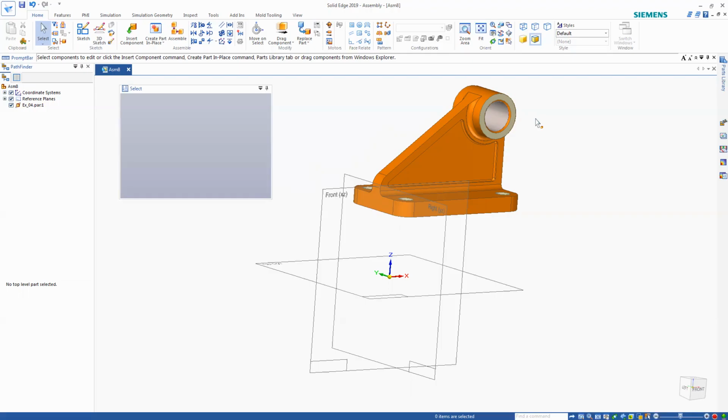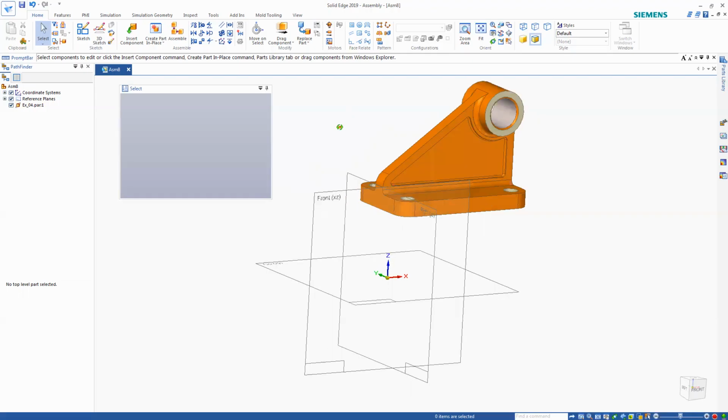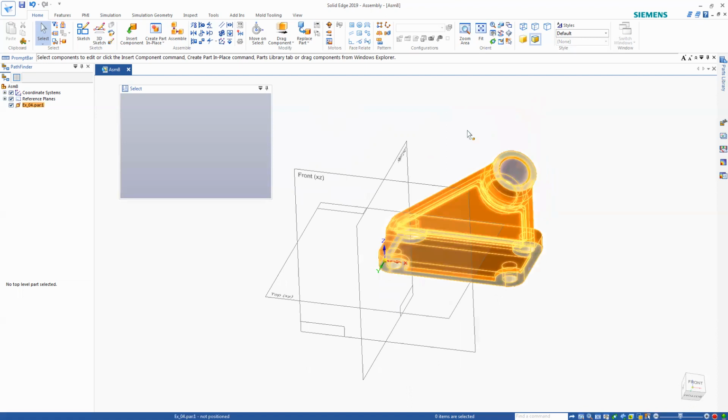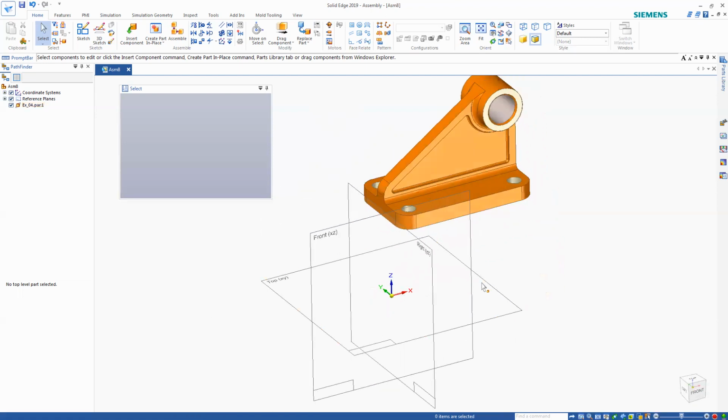But maybe I don't want to do that one. If I want to have it my own way, then I do it that way. Let's say now I want to make sure that this bottom reference coincides with this one, or maybe even this one, right? I can try that one as well. So here I have the other relationships. You see here you have the flush fit. You read that one carefully. What do you mean by the flush fit? Right? Planar align, axial align, and connect.